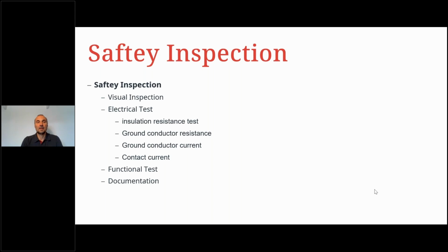And when you have done that correctly and everything is fine on the DC and AC side, do the functional test: switch on the DC and AC switch, do a functional test, and also do documentation about the service exchange.